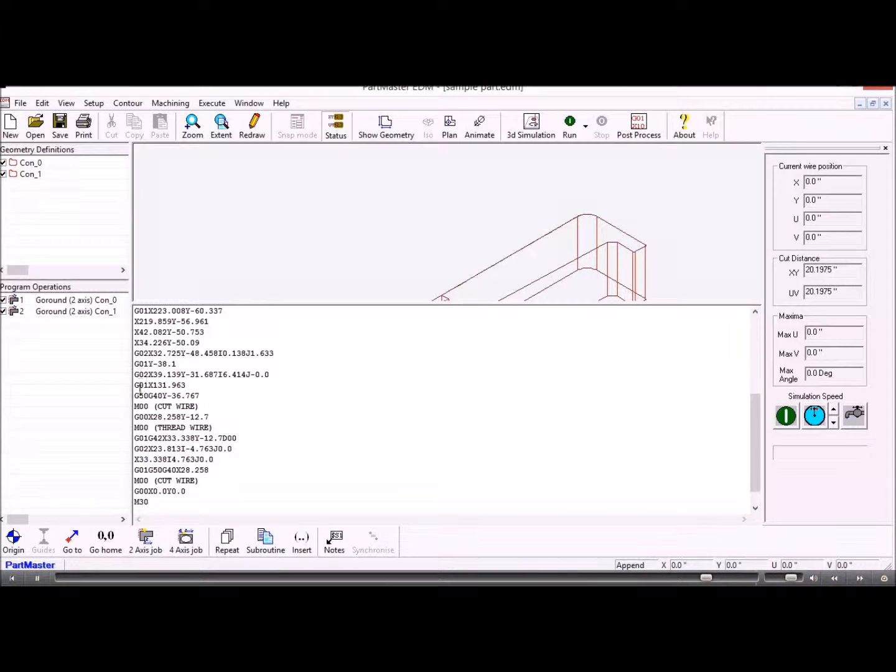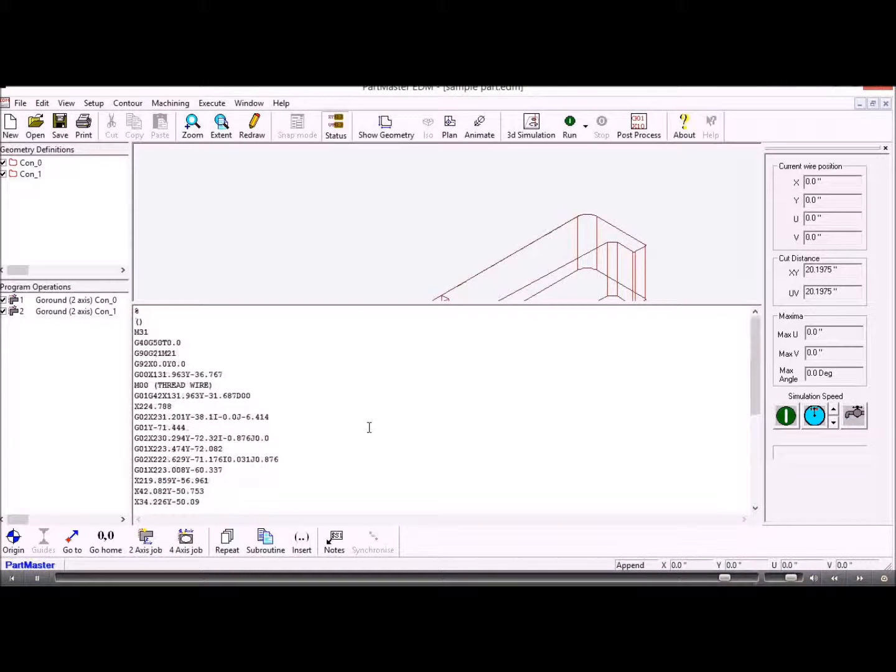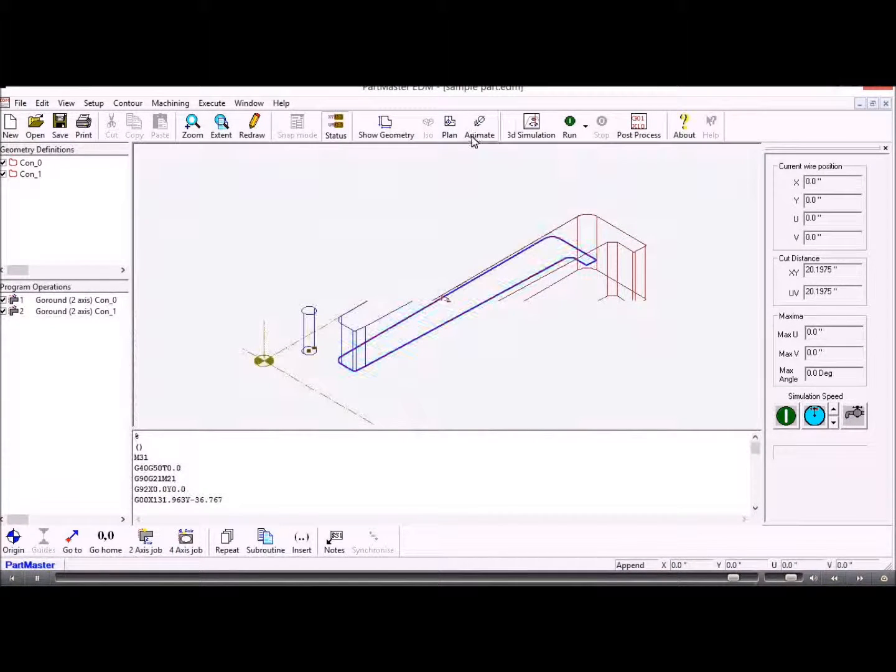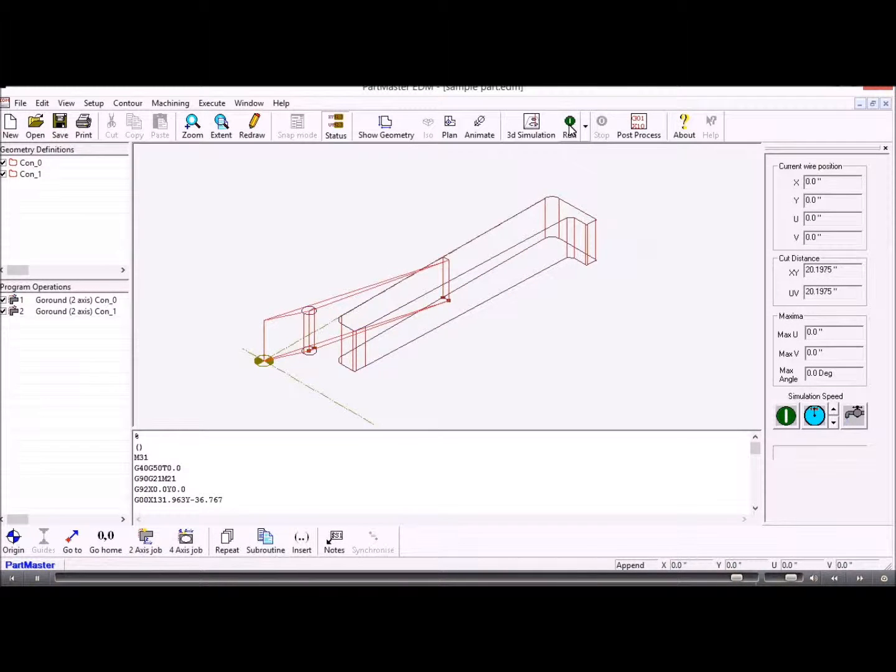And then when it gets round to the end of the first cavity, it gives us the option to stop the machine, cut the wire, wrap it to the next position, and then rethread. And then the same thing happens at the end, cuts the wire before it goes back to the start position. So the post-processor can be modified to output the commands that you need. When we're creating the wire path, we don't produce any technology files or any command files. It's just the geometry, which can then be incorporated into your technology and command files on the controller.